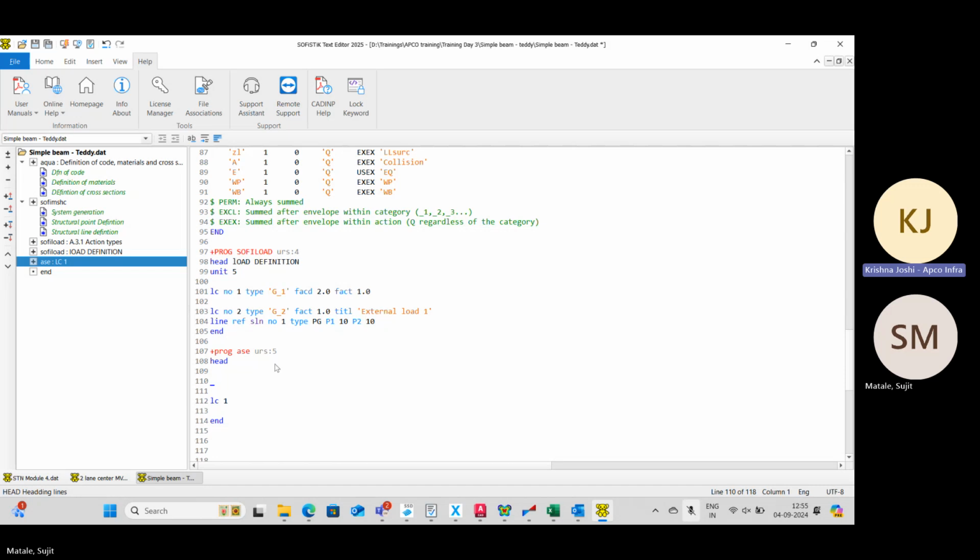So in an impedance test, what you will get is a time history of responses. From that response, you will have to extract what is the time period. You need to take out the data because it is all modes combined, right? The time history that you get has to be filtered to get out the data for one mode in the direction of your interest.